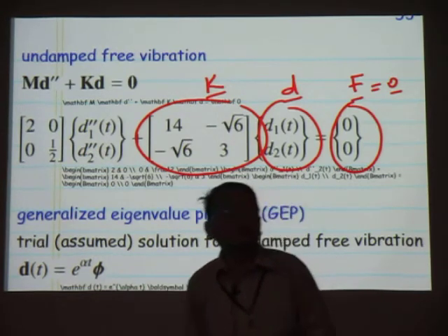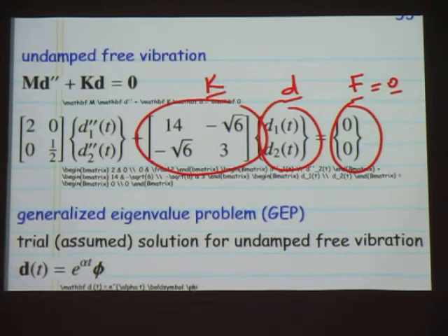What's the method to solve the homogeneous? The equivalent terminology here: free vibration is equivalent to homogeneous, meaning no forcing function. So for a scalar linear second order ODE, homogeneous, you need to find homogeneous solutions.